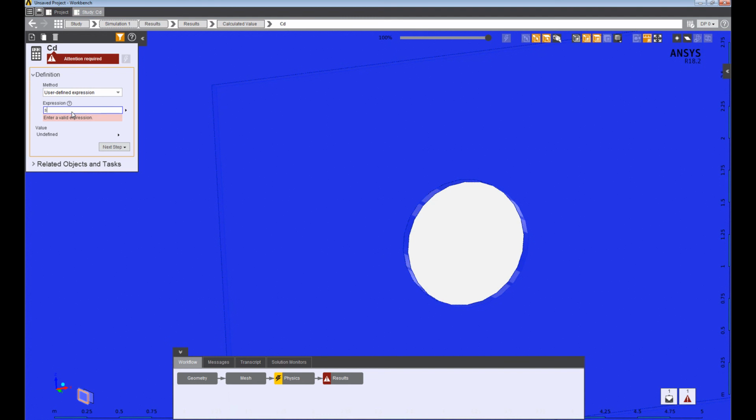And this will be the sum of force in the x direction, comma, and we need to define the location, which uses a Python command called getBoundary, and getBoundary will be using the @ symbol cylinder, and there's an option of various types of weighting, so we'll do a simple sum of the values. So when I hit enter, you can see that it did calculate that force value without throwing any errors. So this calculates the force.